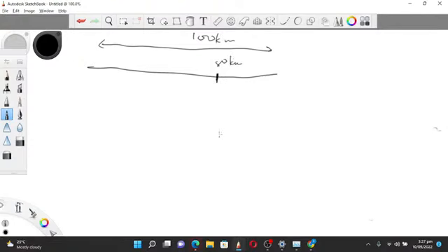The fault resistance. So we have it going to ground from here. Well, the fault occurs at the 80 kilometer point. So that's where the fault is. So we have our fault resistance giving us 10 ohms. Okay. Calculate the fault current.